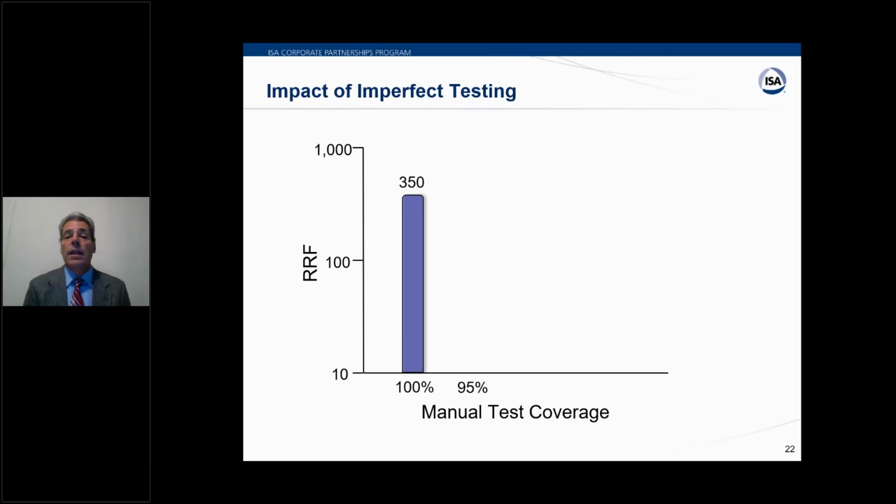Maybe with the valve, we're not actually testing cycle or stroke time. We're not actually testing that it's sealed and stopped flow. So in reality, our test is not 100% effective. If we just assume it's 95% effective, which is grossly optimistic, how much do you think the answer might change? If we're just changing the factor 5%, do you think the answer would only change 5%?